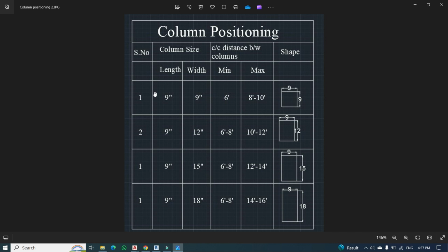Even before columns in the entire structure, in the old houses there were no columns. Earlier there were no columns. So everything was created based upon load bearing walls. What are these load bearing walls? In the good olden days, in the old houses also there was a slab, but columns were not visible anywhere. Why? Because the walls were created with a massive thickness. Instead of 9 inch and 12 inch walls, the earlier walls were 14 inches, 18 inches thick.